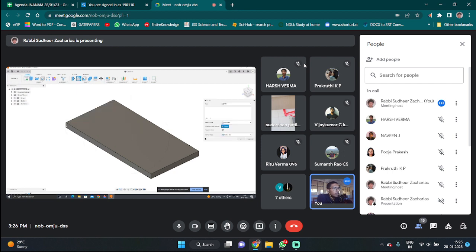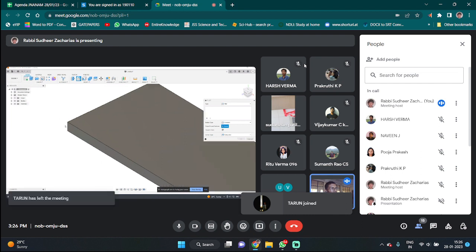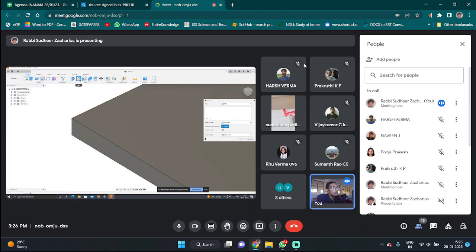And if you want to fillet, we cannot fillet a surface, right? We cannot make the entire surface round. With the middle scroll button of your mouse, you can zoom, you can move it up and down to zoom. So now if you want to do the fillet, you can just select the edge there, and then you can type in the distance of how much you want to reduce, or you can just use the scroll option here.